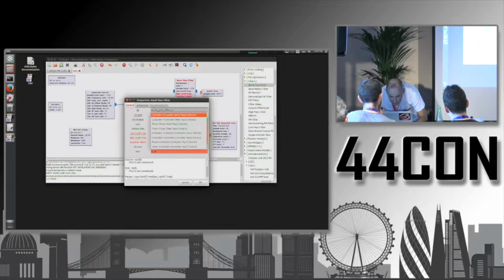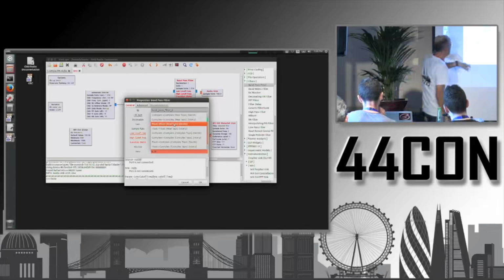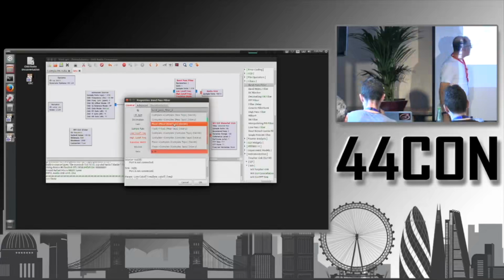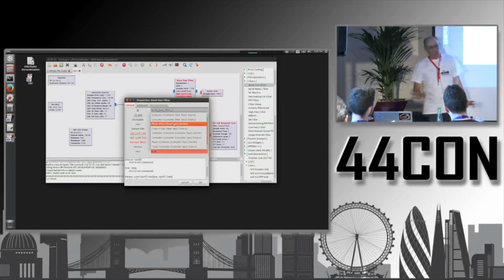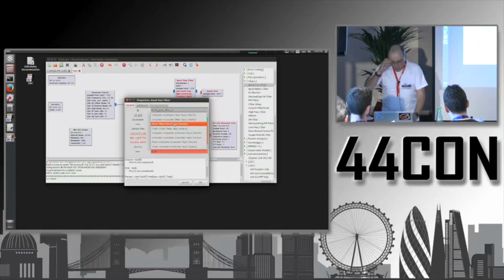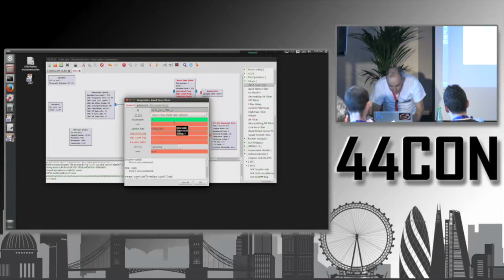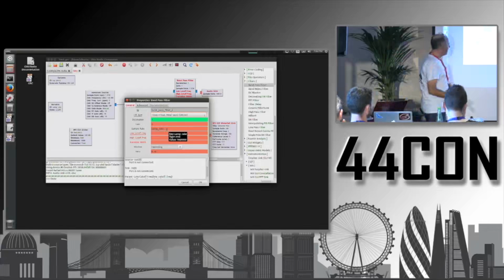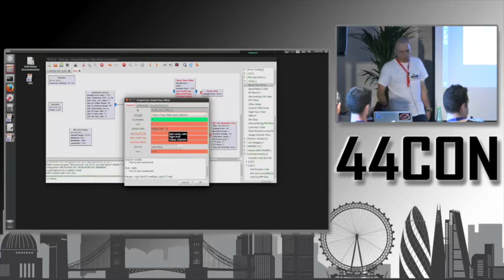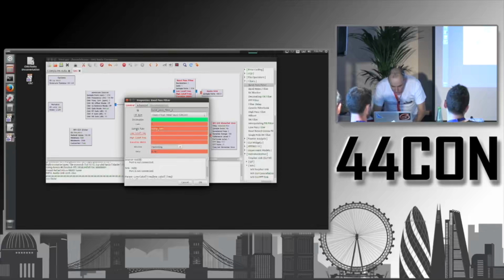So here you select float, from a floating number to a floating number. You have two options with decimation and interpolation. We are not going to set those parameters, so you can just select decimation and leave the default values. And we are not going to do resampling or amplification with gain or things like that. So just float, decimation. Here the sample rate 48,000.